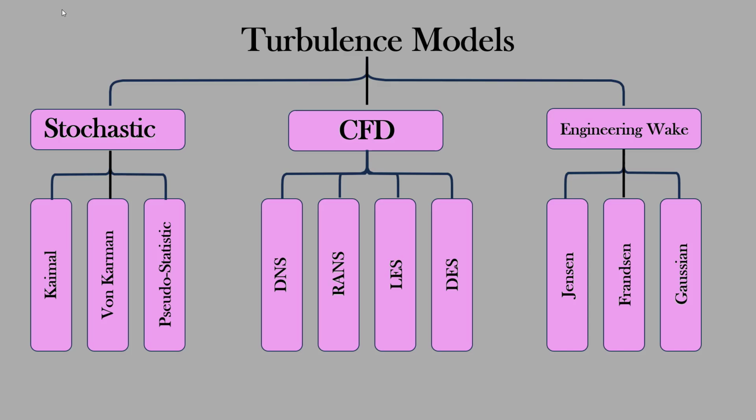Meaning that because one of these is computationally expensive, for example, LES is computationally expensive, DES actually solves it. And because RANS is not as accurate as LES, DES solves the problem of RANS. So the cons for both of these approaches are solved using DES, and from there, you are then able to have a more workable solution.